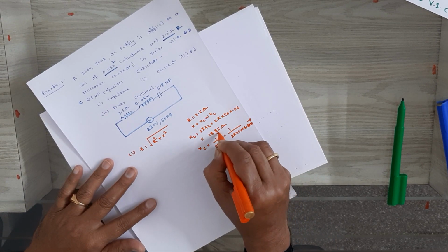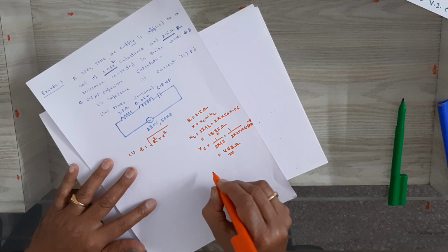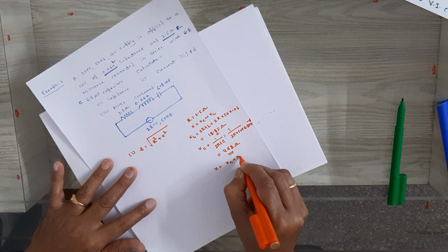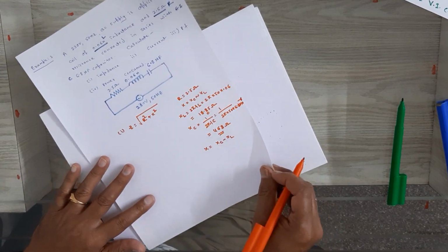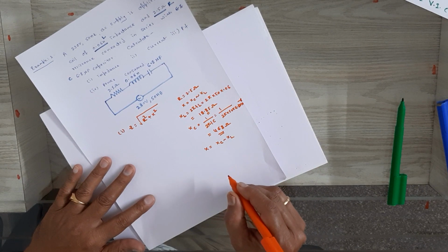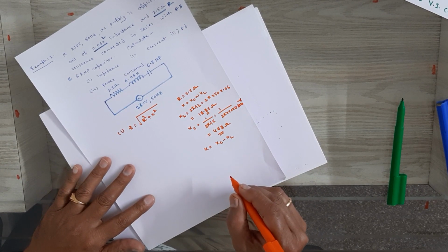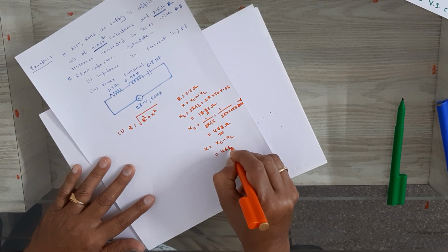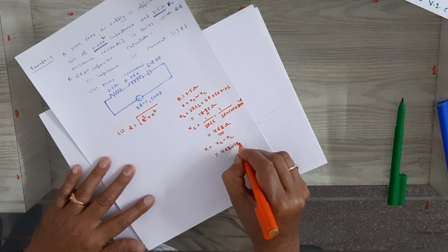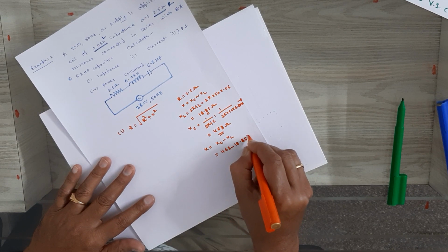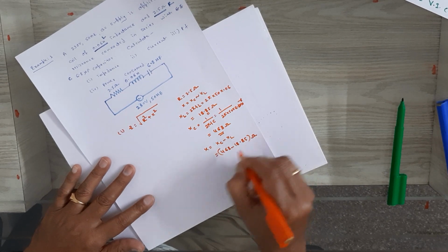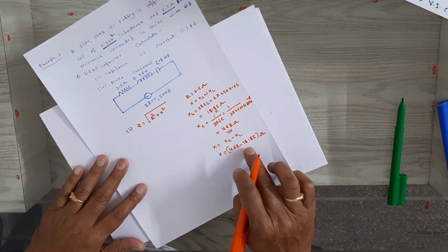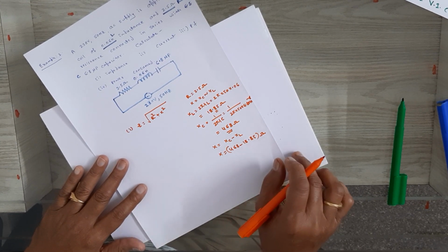See here, you have to compare the reactance. It is 468, it is 18.85. Therefore, your X will be XC minus XL because XC is greater than XL. The effective reactance is the difference between these two. That is 468 minus 18.85. That I will keep as it is, or you can simplify by deducting 18.85 from 468.